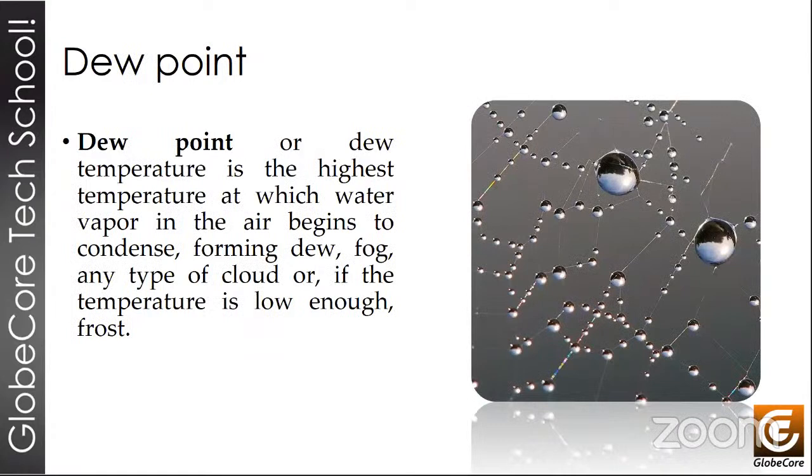The dew point measurement. Now, the dew point of a gas is defined as the temperature at which the moisture begins to condense and precipitate on the surface that contacts the gas. Based on this value, the total amount of water it contains and its relative humidity can be determined from a known volume. So the amount of water in paper is determined as a function of the relative humidity of the gas with which it contacts when it's exposed until equilibrium conditions are reached between the respective moisture levels.